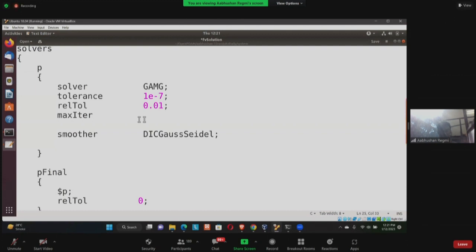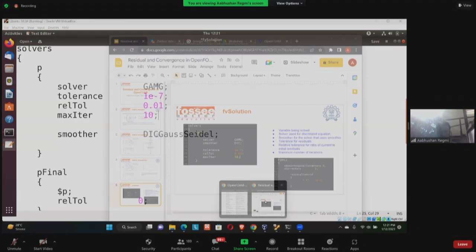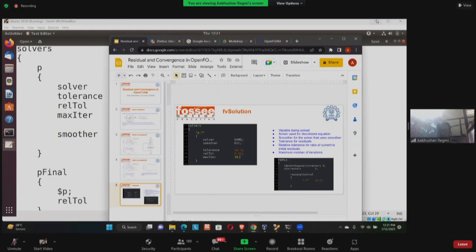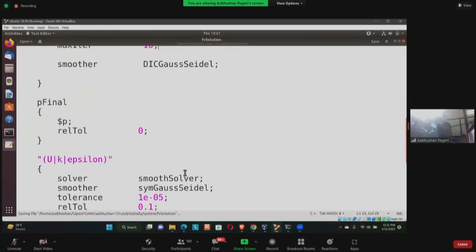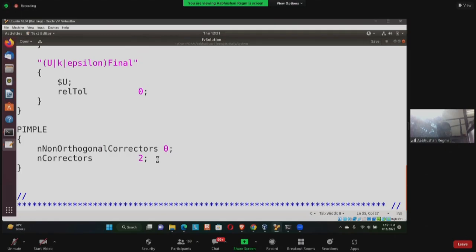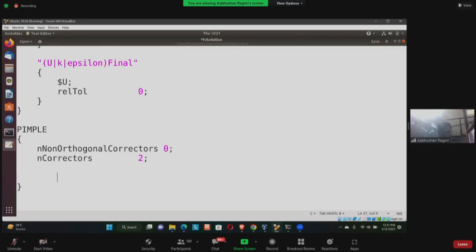Okay. So I'm going to give it some value, let's say 10. Let me just check, maxIter 10. Yeah. Okay. Now at the very bottom inside my PIMPLE dictionary, I'm going to add this line.